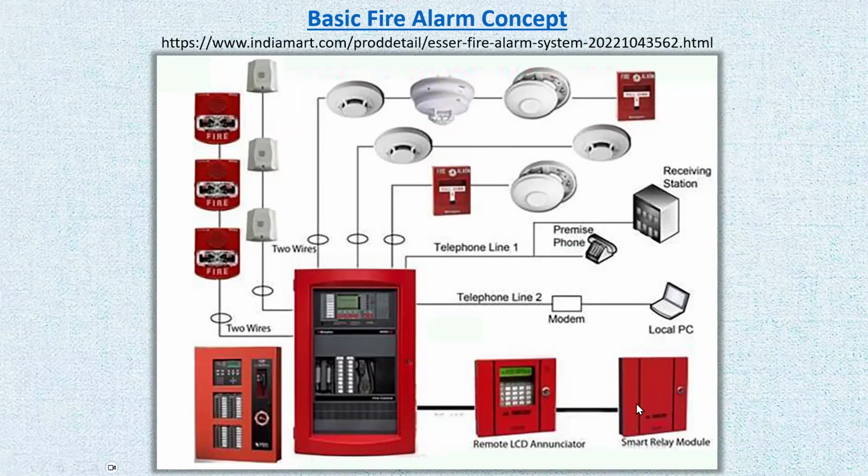And there are some relays that can trigger other things, like shutting down the water supplies, shutting down gas supplies, or whatever, based on the fire alarm triggering. So there are all kinds of different interfaces that can be interfaced with the main panel.